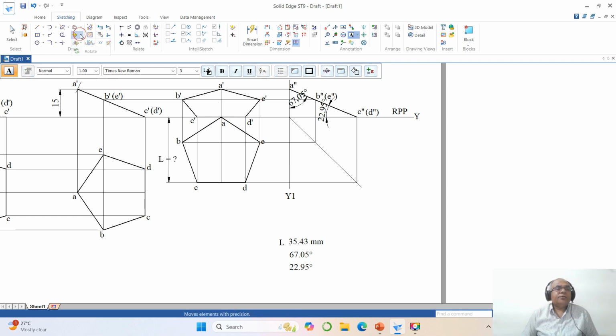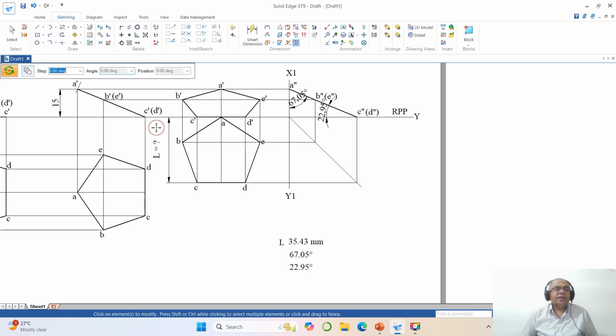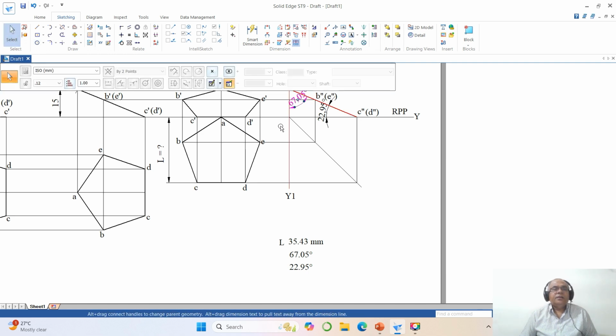Then you rotate this, go to rotate command, disable copy, select this horizontal line which has to become vertical, then go to move, select this and keep it here. Now you go to this and make this line blank. I don't want text to be seen there. Similarly here I don't want the text to be seen, blank.